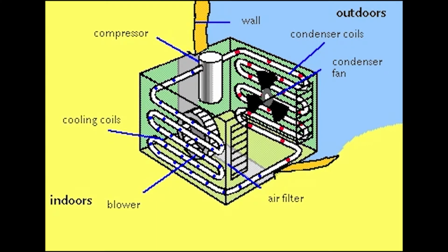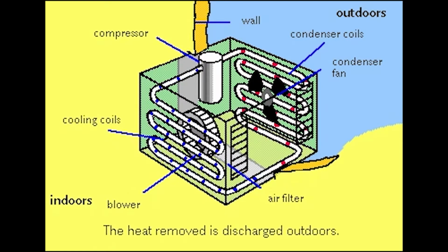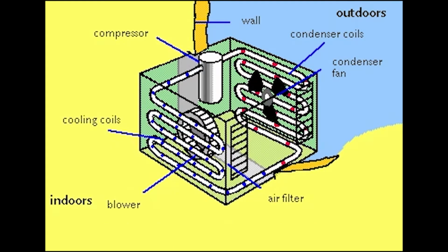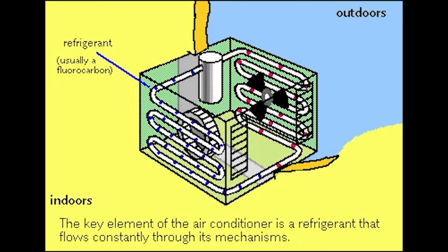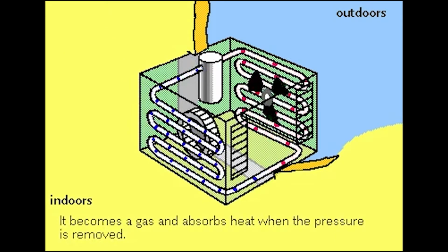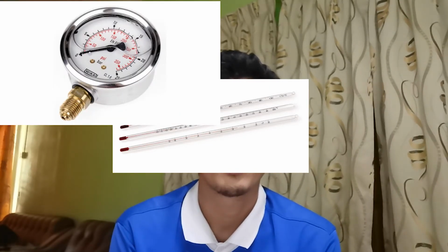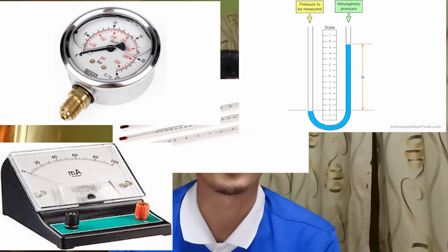For the second experiment, it used the condensate water and a heat exchanger to lower the discharge temperature of the compressor and to generate the subcooling. Next, the use of condensate water will reduce the power consumption and increase the cooling capacity. By lowering the compressor discharge temperature using condensate water, it will reach subcooling at the condenser outlet because some of the heat has been absorbed by condensate water before entering the condenser. The subcooling causes the increase in cooling capacity of the air conditioning. Lastly, there are 5 instruments employed to measure those parameters, which are thermometer, pressure gauge, manometer, ammeter, and voltmeter.